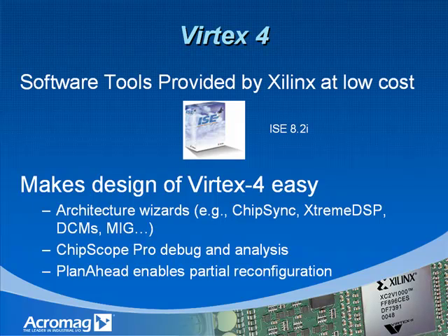The Virtex-4 software tools provided by Xilinx are low cost. They make design of the Virtex-4 easy. They have architecture wizards for ChipSync, Extreme DSP, DCM, and memory interface generation. ChipScope Pro is also a tool provided for debugging analysis, and they include the PlanAhead tool, which would allow partial reconfiguration of your FPGA, saving many hours of configuration time.